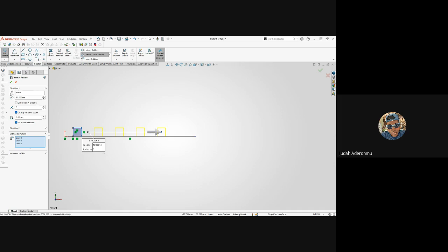I think it's Fusion that does that, not SolidWorks. I think in SolidWorks, you have to actually set distance. It's Fusion where you can decide the endpoint and just distribute equally along that area.